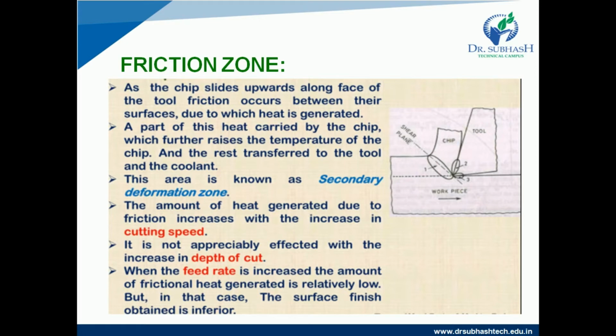A part of this heat is carried away by the chip, which further raises its temperature, and the rest is transferred to the tool and the coolant or cutting fluid we are using during the operation. This area is known as the secondary deformation zone. In another way, we can say the friction zone is known as the secondary deformation zone.